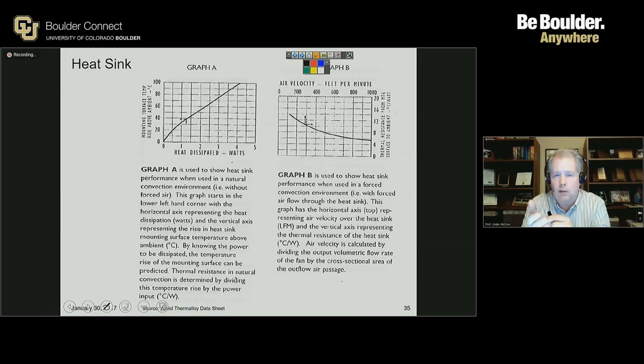A smartphone can be a very challenging environment, because if you think about the electronics in a smartphone, they are typically in some type of sealed package which does not allow airflow. And so you have to deal with the fact that temperatures are rising in that cavity and that you're stressing those components harder than you might have to if you were in an open design.